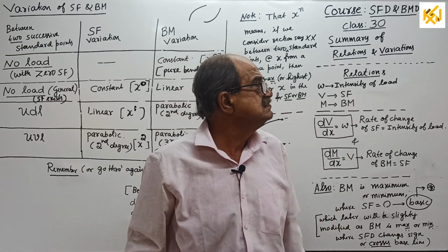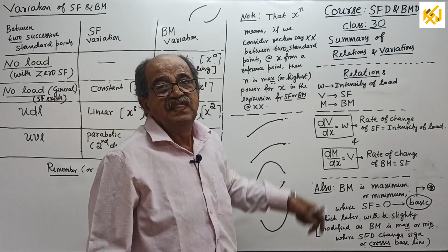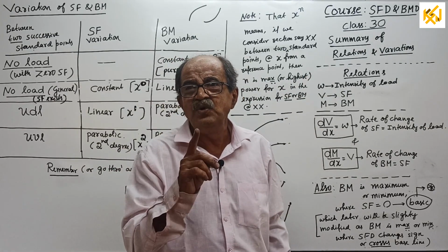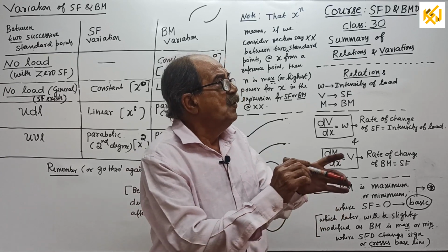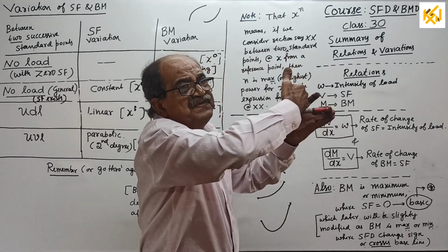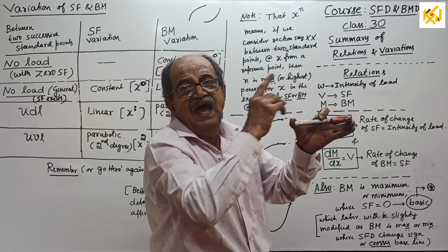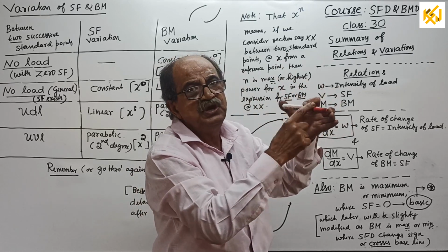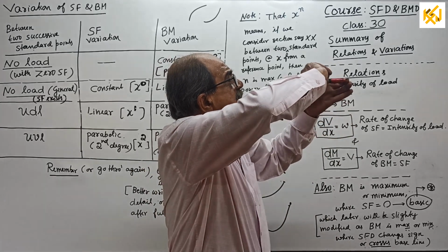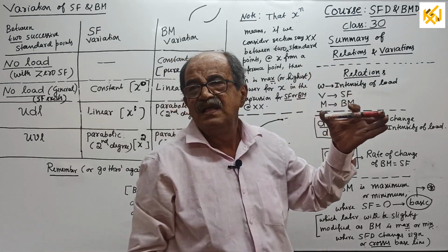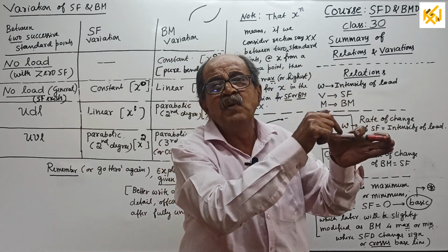Okay, adjust it. Now, further. Now the most critical part I will tell you is what? The explanation and understanding. If a point load is acting somewhere, then at that point you have to find the shear force twice. I will explain why. Whereas, if a couple is acting, then you have to find the bending moment twice.